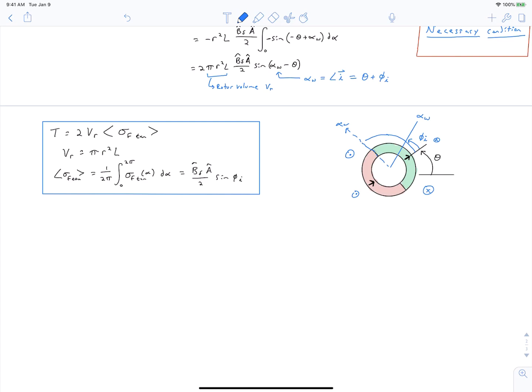And if you go back and compare this against the Lorentz force law, you can see that this indeed is going to maximize your torque because you've got the maximum amount of field cutting this conductor over here and this conductor over here. Okay, so all this is building up our physical intuition and a sanity check on what we're about to do for bearingless motors. This matches the machine design sizing video that we present in the machine design course.